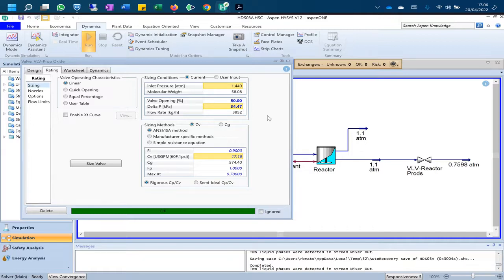These two values are established by default by HDS when designing new valves, because a 50% opening allows closing and opening the valve to allow lower and higher flow rates, and this value of pressure drop is high enough to control the flow rate in the pipeline, but is not excessive to produce excessive energy demand.